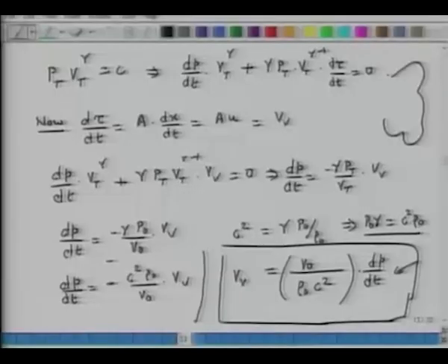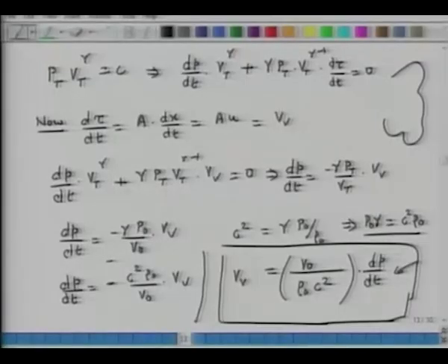So what that means is that even if I do not necessarily have a long tube, but it could be any closed volume, it could be an arbitrary sac like this, as long as the longest dimension of this sac is significantly less than lambda over 2 pi, the volume velocity at the exit point will be related to change in pressure in such a way, and it will behave as a spring, as a mechanical spring.